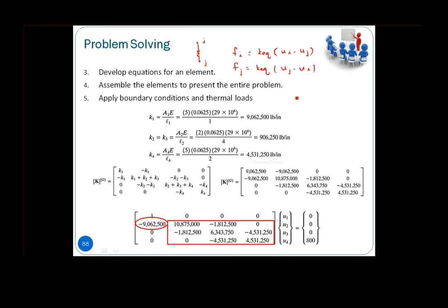So at the end, in matrix form, we have Fi, Fj, equals the 2 by 2 matrix K_eq, negative K_eq, negative K_eq, K_eq, times Ui, Uj.